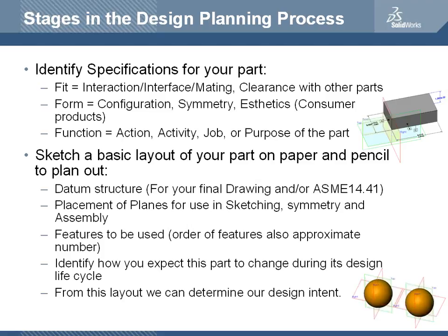And finally, for an assembly, if you have a complicated part or an ergonomic part especially, and you don't have very many planar faces on it, when you go to mate it up in the assembly, if you take a sphere for example, there's not a whole lot of mates that we can apply to that other than tangency and concentric. However, if our planes are in the right spot, we can utilize those planes to create distance offsets, coincident or parallel, what have you.